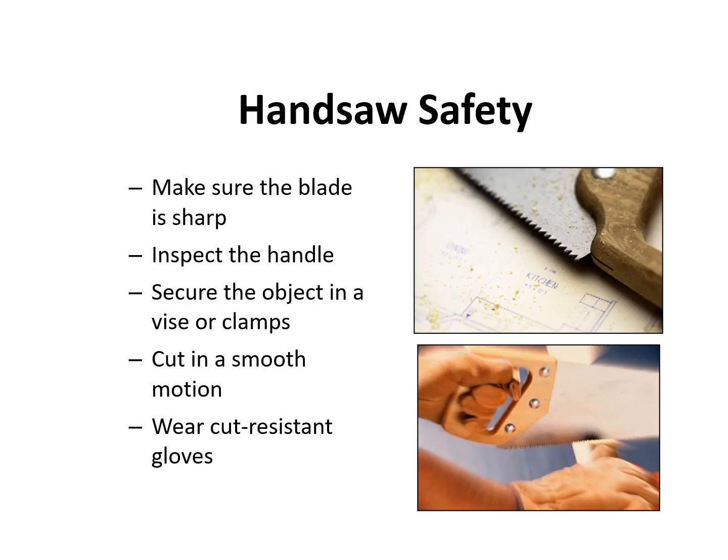When using a handsaw, make sure the blade is sharp. If not, sharpen the blade or replace it. Inspect the handle on the handsaw for signs of damage. Make sure the object you are cutting is in a vise or clamp. Cut back and forth in a smooth motion. Wear leather work gloves or cut-resistant gloves when handling saws.